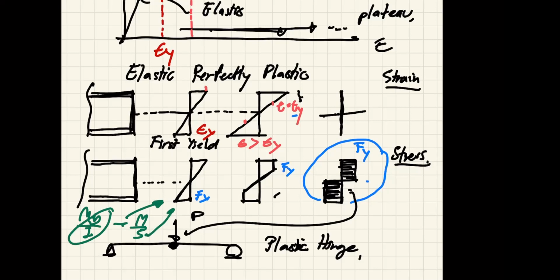But because we know that our beam can take more punishment, we are going to use this stress distribution in our design. We are not going to use the elastic section modulus, but the section modulus derived from this stress distribution. This stress distribution will give us the plastic section modulus.